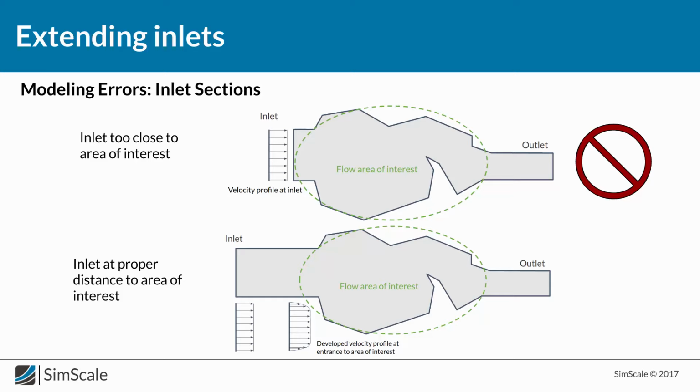It is especially important when we are talking about big sections of ventilation systems and when our inlet is happening exactly after some kind of a knob or an angle. Any kind of angle that is positioned within a flow like this will create a different inlet profile and should be included within our model to properly represent the way air enters our domain.